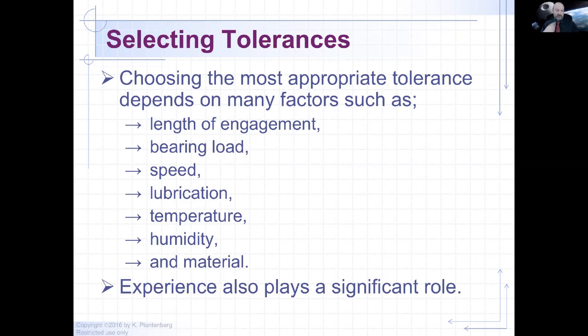And then the speed. How fast is the shaft going to go in, or how fast is it going to rotate within the hole? The temperature, think about it. If the temperature decreases, the shaft gets smaller, but so does the hole. Or does it? No, the hole gets bigger. That's right. So the shaft will shrink, and the material that the hole is in will also shrink.